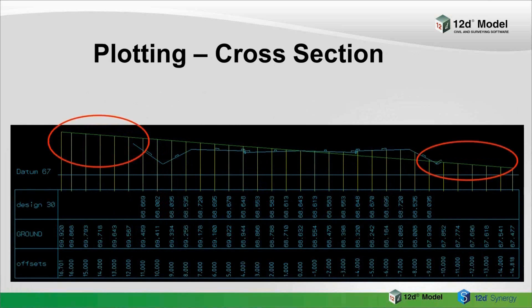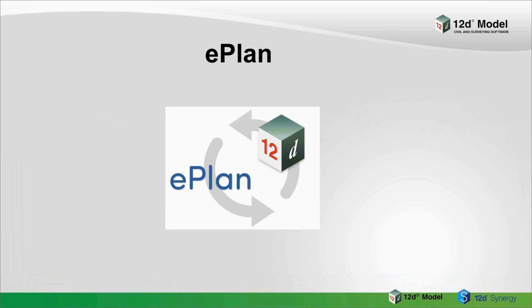And here's one where we've just got regular intervals only, also going out in your left and right extension areas. Obviously, this sort of regular interval is great when you've got natural surface cross-sections which could have hundreds of points in it, so it makes it very hard, and you don't want to label them all.